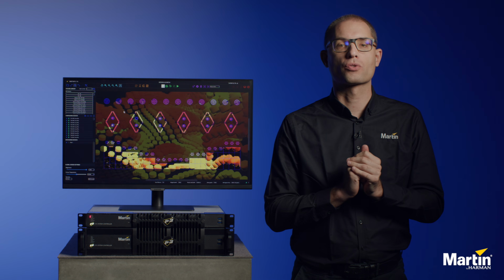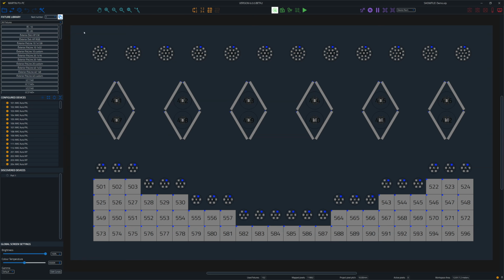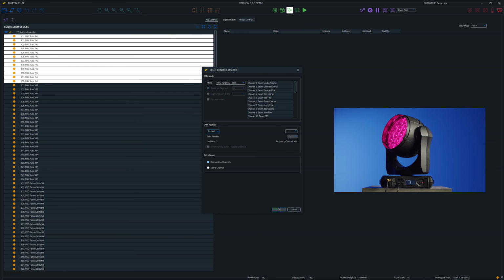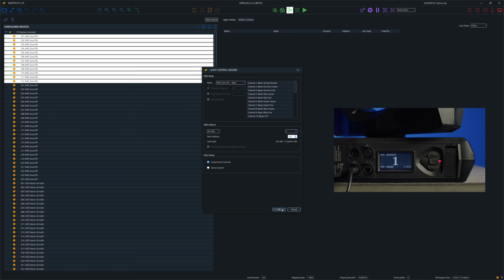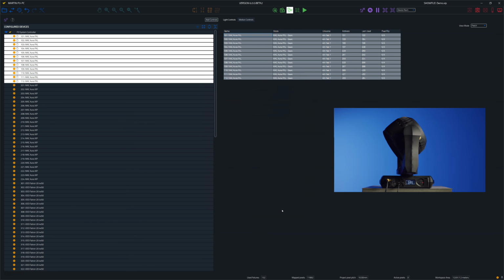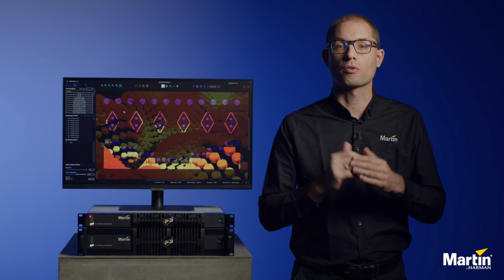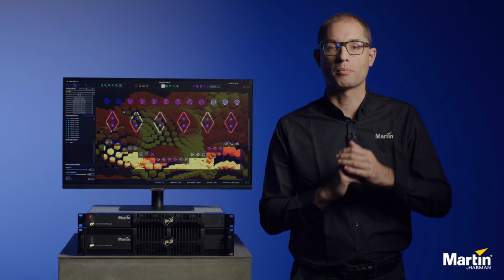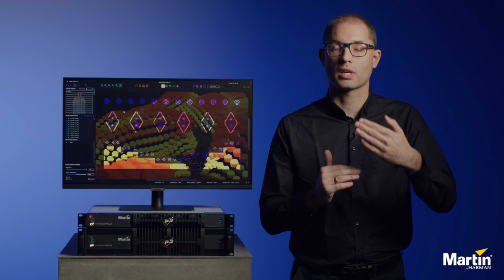If you also want to control the fixtures from a lighting console, you can easily patch them via the P3 system controller. Simply select the DMX mode and start address, and the patch is done. No need to walk up to the fixtures and do anything locally via the display. Many fixtures also enable you to freely create pixels or segments to be controlled from the lighting desk, or even invert the pixel order for fixtures hanging upside down.